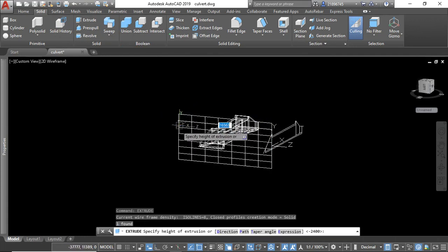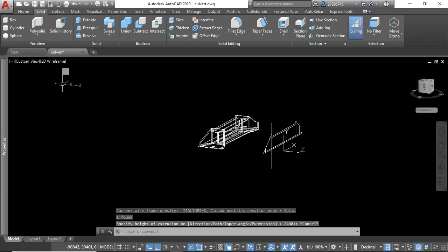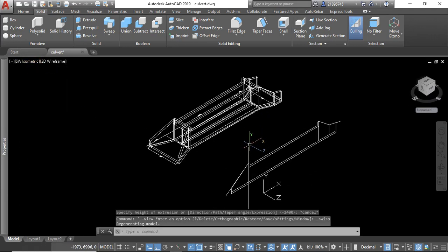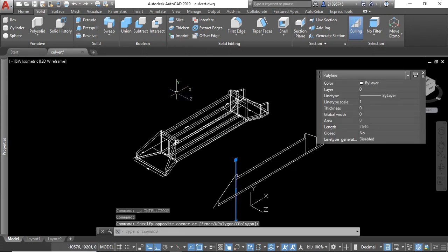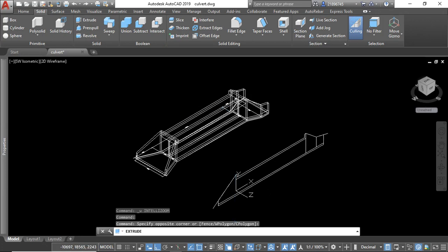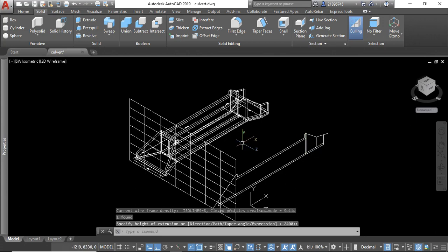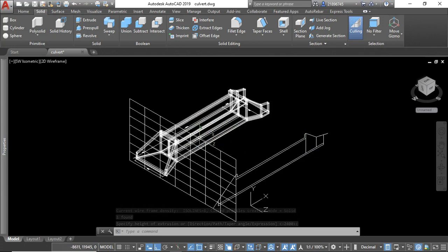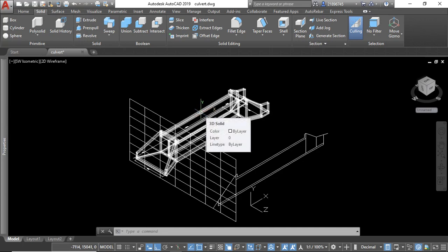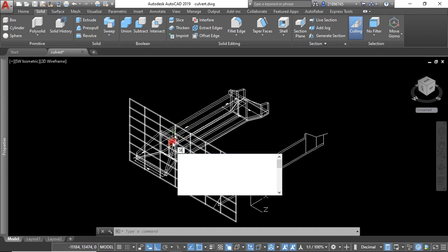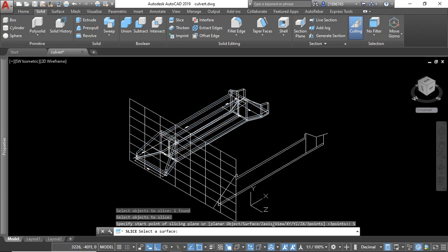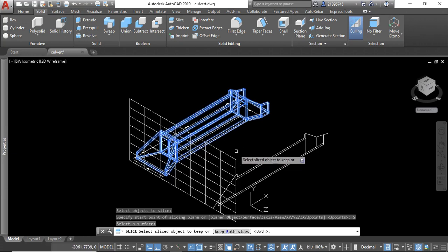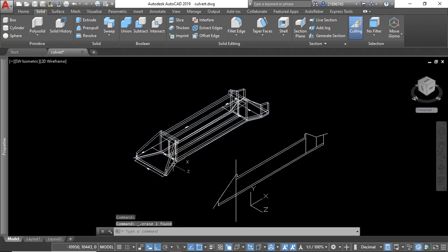Extrude. I think, are we on the right plane? If yes, you want to be sure that we are on the right plane. Let's do this again. Let's do extrude here like that. We can now come here to this whole complete 3D solid. So we want to slice it so that we have the two parts different. So we slice. Yeah, this is what we want to slice, and we want to use the surface. Okay, so enter. So now this part is different.